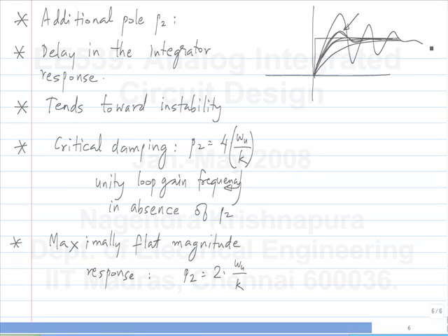So this could be an amplifier. It could be, not an explicit amplifier, but something like a voltage regulator. Things like this are important because a voltage regulator is supposed to hold the voltage despite changes in load currents and so on. So a change in load current is like a step response applied to some point. It's a step current that's applied to the output. Now, when you have a step current applied to the output, the voltage is supposed to be held constant.